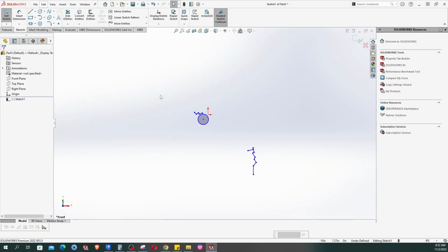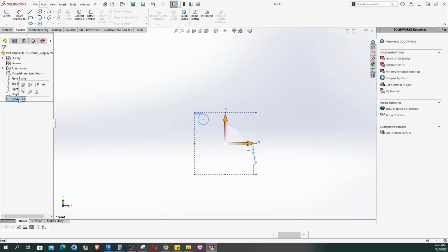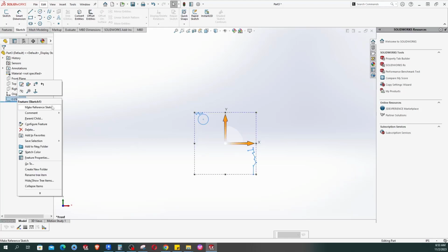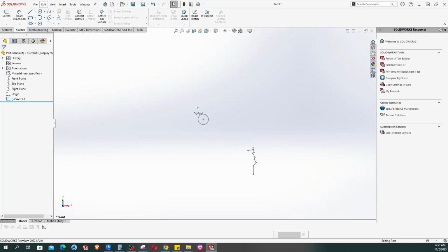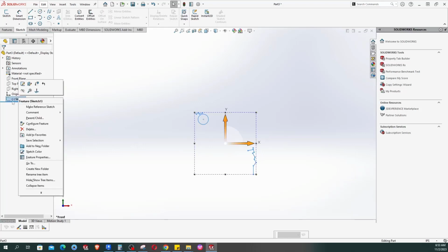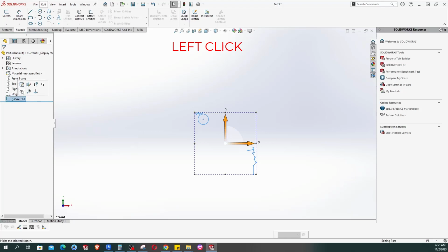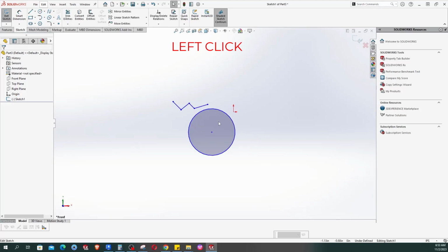So that's how you create a sketch in SolidWorks. If we click this one, the exit sketch, our sketch will be saved, and it will create a sketch feature here. This sketch is called Sketch1, and it's a sketch feature. It comes from here in the command manager. Now let's do a recap. Let's delete this one. By the way, if you want to edit the sketch, you can always go back. Just click it once, and then an edit sketch option will appear. Click it, and then you go back to sketch mode again.